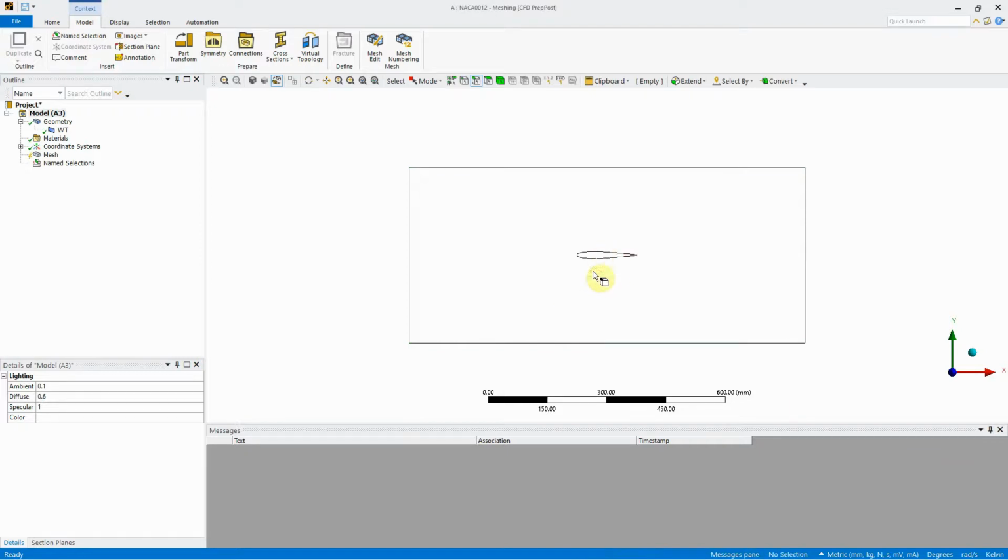There is another function: if you've got multiple edges, you can come up to this section here and select box select, and that will select them here, or you can go single select where it grabs them individually. Switching between single select and box select, there is a way of doing it on the mouse itself.